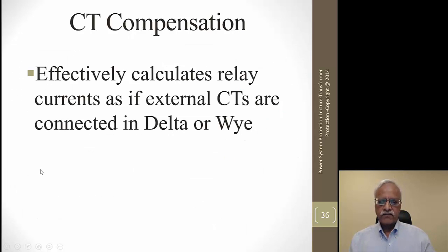Okay. Relay compensation, essentially what it is doing, it effectively calculates the currents as if external CTs are connected in Y or delta. That is what the basic intent is, to take care of the phase sequence of the relays.